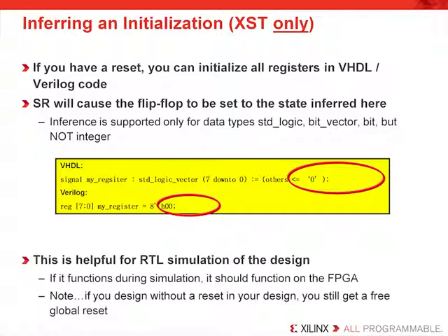Now, this is mandatory if you design without a reset on the circuit. Inferring an initial value only works for data types of std_logic, bit_vector, and bit, but does not work for integer types. Now note that this inference is currently not supported for Spartan-6.